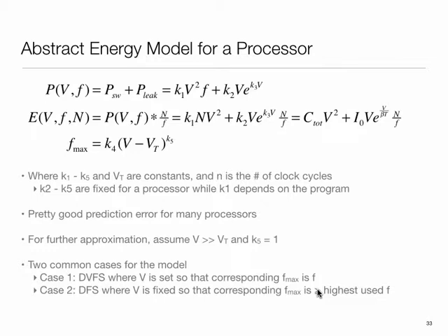If I operate it at 1 amp versus half an amp, my effective capacity, that is how many joules I will actually be able to extract out of it before the battery effectively dies and has some unused chemical energy in it, changes. And usually batteries do better if you draw energy from them at a lower current. So there are those advantages which come into play.